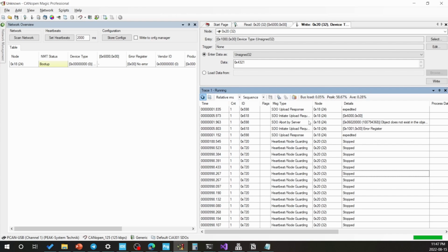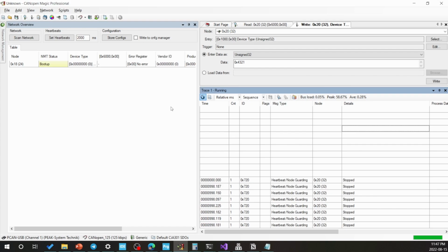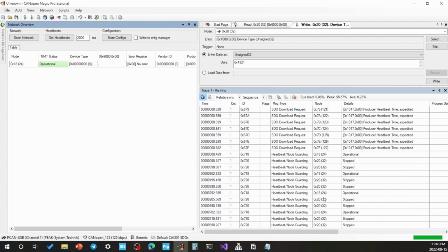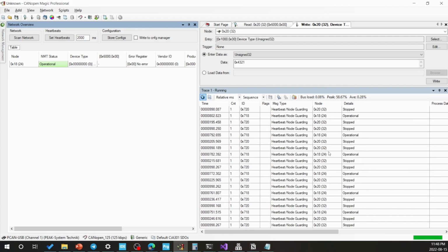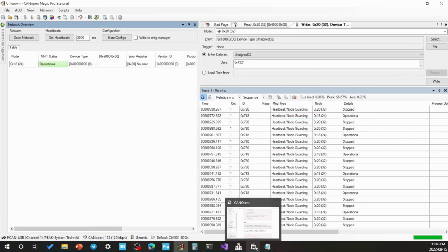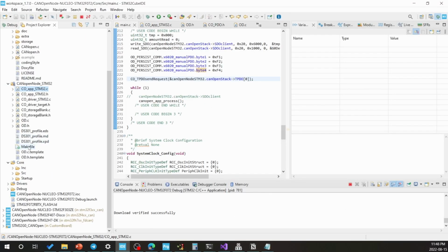Actually, that's something else. Where is this coming from? RPDO guarding. It's the rest of the nodes, they are all in stop mode except for this one. And the thing is, why does this one not trigger TPDOs? There's something wrong.